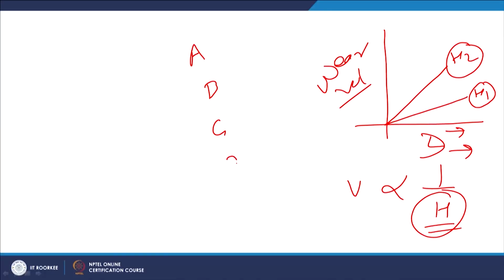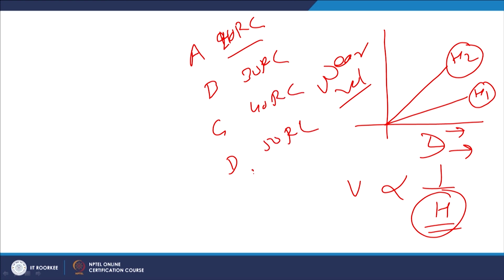If we take, say, 4 different materials of different hardness values, like 20 RC, 30 RC, 40 RC and 50 RC, and then we try to see the wear behavior, we may find that there is some kind of consistency: with the increase of hardness, there is a reduction in the wear volume. So, under simplified conditions, normally this law behaves like this, where the wear volume is found inversely proportional to the hardness values.